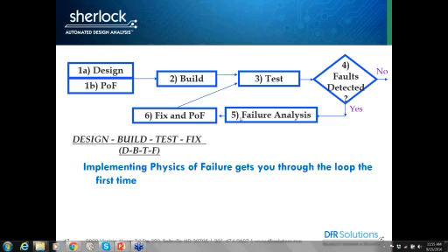Really, I would say the limitation for IPC TR-579 and any sort of FEA tool is that you're looking at isothermal conditions. You're not able to take into account thermal gradients being imposed on your circuit board during the temperature change. So once you get over a ramp rate of 10 seconds from -40 to 105, you're pretty much taking something from some type of Fluorinert type of fluid, and you're just plunging it back and forth, liquid to liquid.